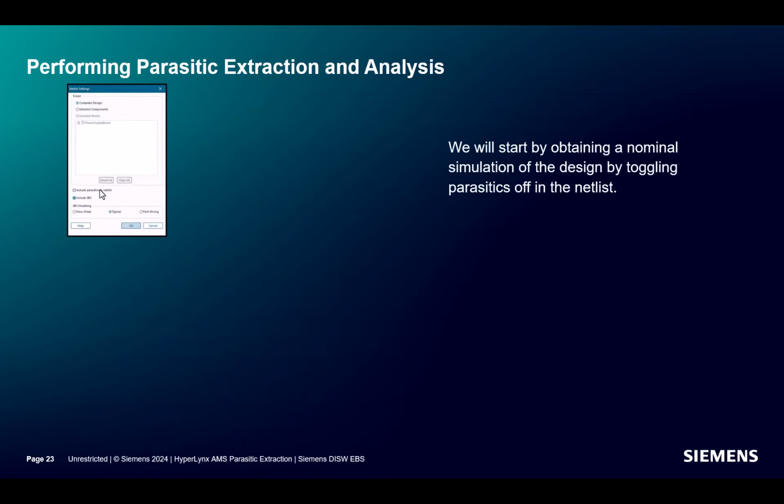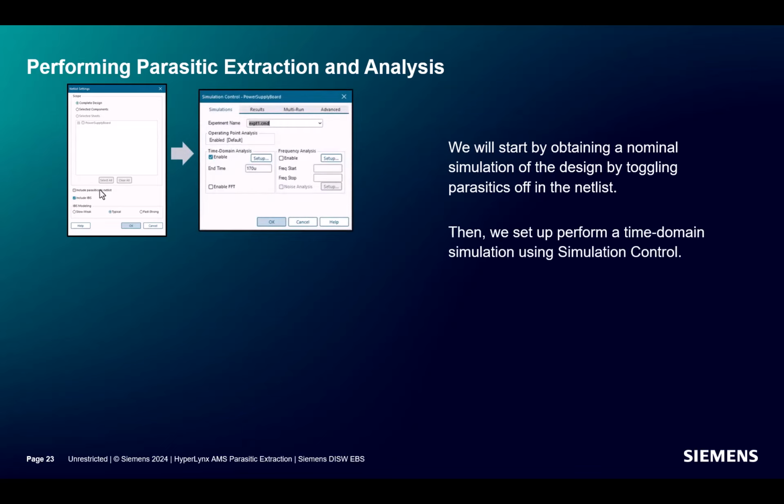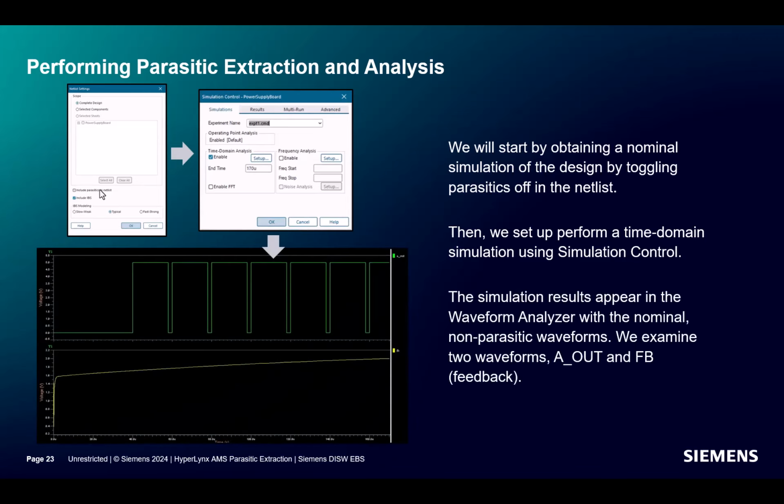We will start by obtaining a nominal simulation of the design by toggling parasitics off in the netlist. Then we set up and perform a time domain simulation using simulation control. The simulation results appear in the waveform analyzer with the nominal non-parasitic waveforms.